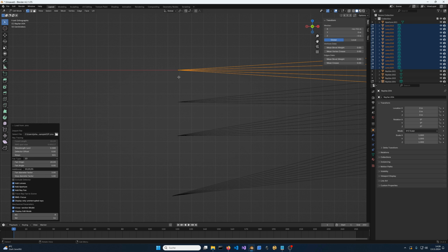For this lens, we actually can see that there is some back focus increase for higher field angles. So when you set this lens up for use with Cycles, for example, for rendering in Blender, you might want to set your image plane somewhere along the middle of this, or if you want to focus at the center, or if you want to focus at the outer edge, you're going to have to set your sensor a little differently. Now, however, a word of caution with this example.